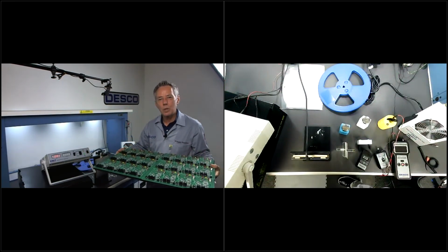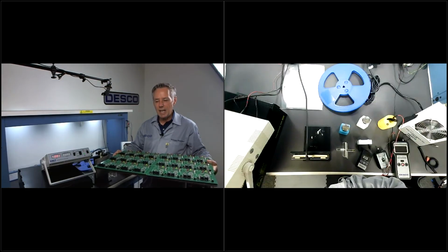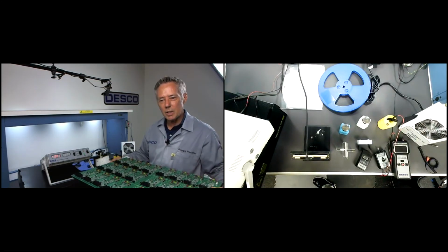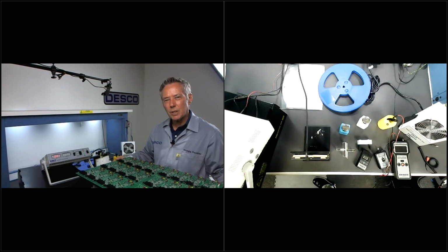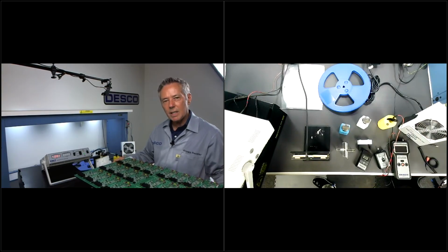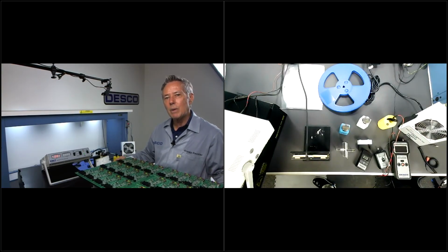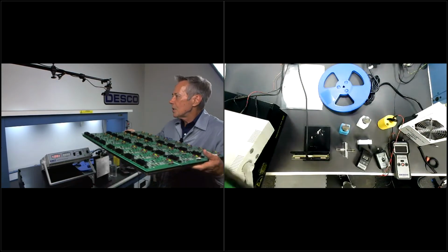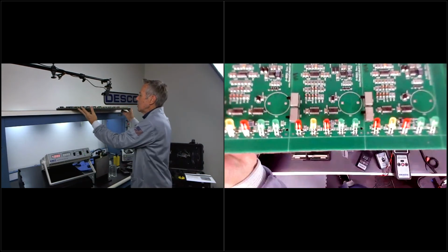If I was wearing a wool sweater in the wintertime, for instance, and I was walking across the floor with this tray, I would induce the charges from my clothing onto these circuit boards. Or in other words, I would be violating that 12-inch 2000 volt rule or that 1-inch 125 volt rule. So what ESD smocks do, especially a good one like this that's very conductive, is they act like an ESD bag to keep the charges from your clothing getting out. So that's a perfect example of a smock.